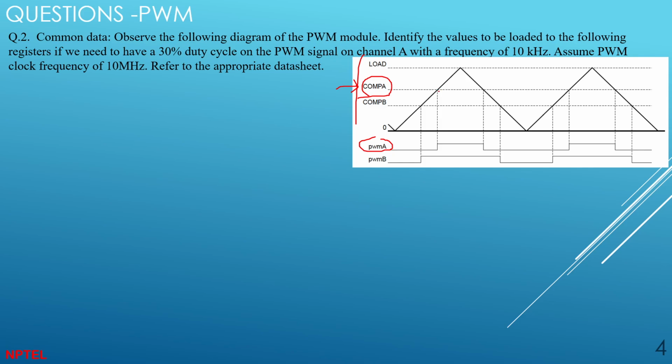It's a comparator. It will check a value. If a value is met, then it will send a signal like this. And this is what the PWM signal is. If you change this width to here, then the pulse width will change. Change to this, the pulse width will change.